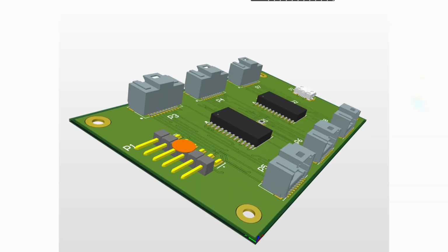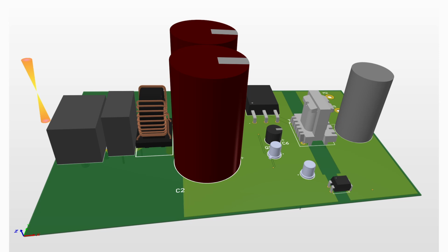There are ways that we can tackle common mode emissions at all three levels of the design, including your circuit design, PCB layout, and the assembly level. At the PCB design level, the main thing we can do to combat common mode noise is to reduce the impedance of our ground plane as much as possible. In this case, the impedance of the ground plane refers to not only the resistance of the ground plane, but also the inductance as well.